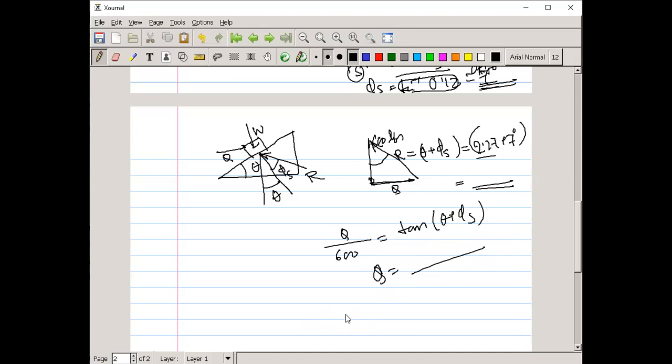And now in the question it is given how much torque is required to rotate the worm gear. So the torque is nothing but Q into the worm gear radius, no? Worm gear radius. So that is Q into 0.15. No, sorry, 1.5, that is 1.5. So you can get the torque. That is your answer.